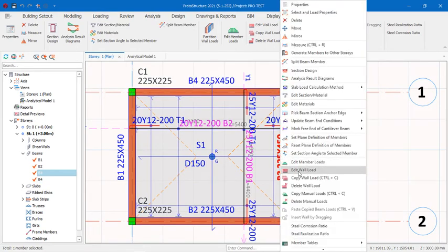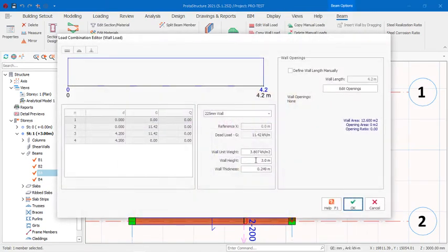Now let's say from the software we have a wall load on this beam already. So let's use the exact wall load. This is the member load. I have assumed 3.0 height, and this is the wall unit width for my wall, 3.8. I modeled a 225 mm wall with plastering on both faces. That's how this thickness came about. Like I said, I won't go into details of modeling. I'm sure you can find enough videos on YouTube that will take you through that.